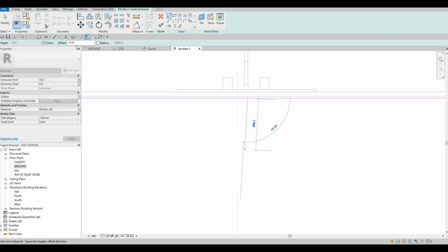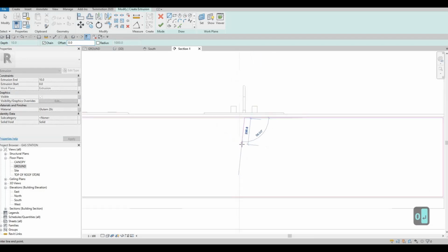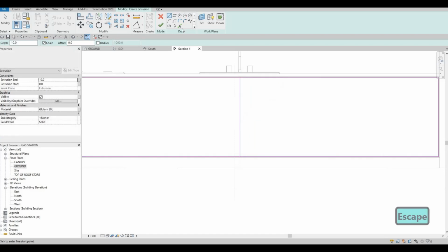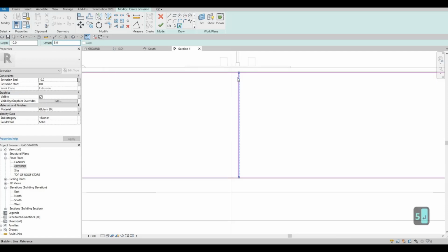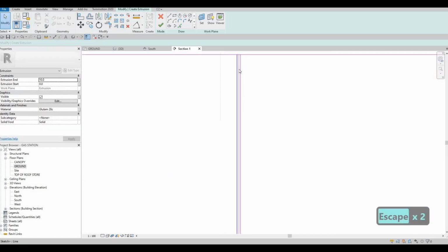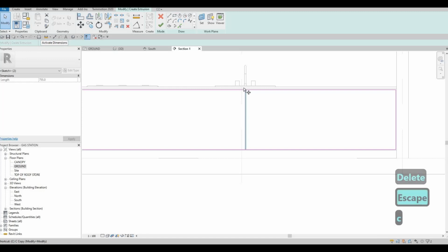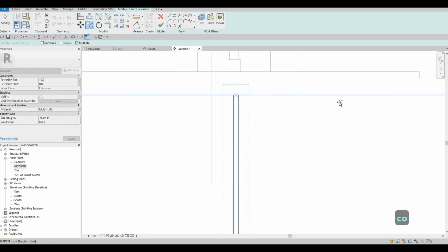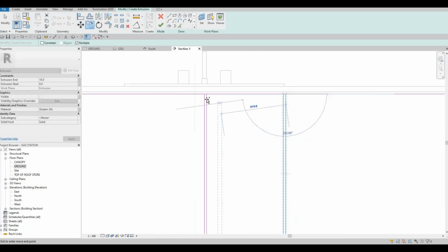So now let's go and create. I will need to make this one 0 and then just add it in the middle right there. Just estimate it. And then pick a plane, put 500.5, and then click it in the midpoint so that we have exact 10 offset of each. And then now we just need to copy it, CO, and then grab it and then just add it on the outside right here.